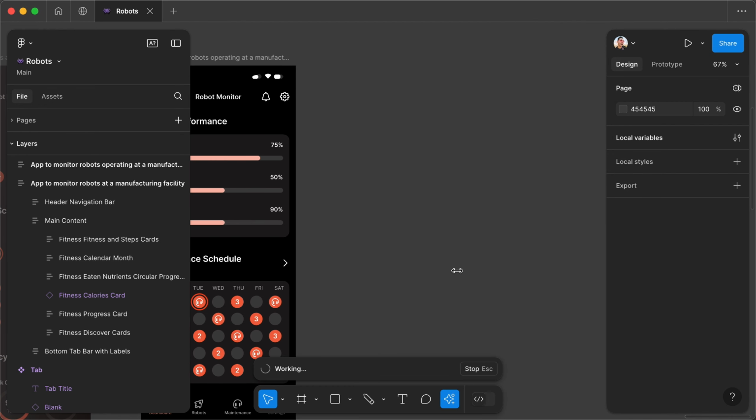Watch carefully. Firstly, select the icons and use the native Figma feature, Create Multiple Components. Secondly, press Command-D or Ctrl-D on Windows to duplicate these components as instances. Finally, press Shift-Tab to select the main components again and simply drag them out somewhere, leaving the instances in place.